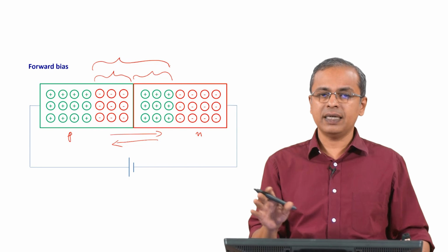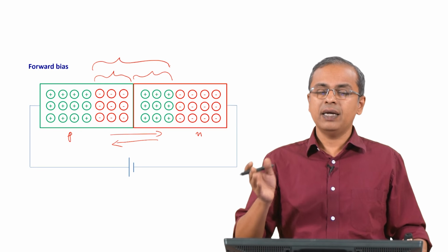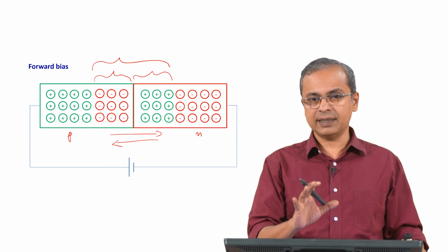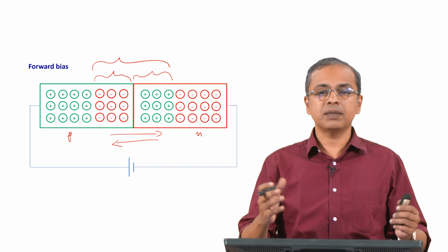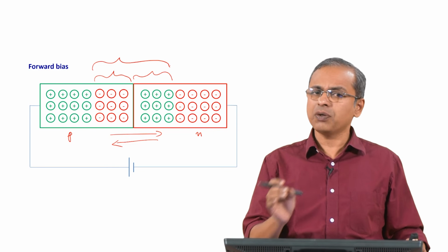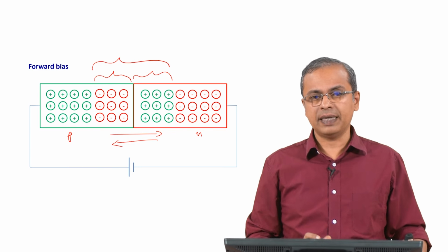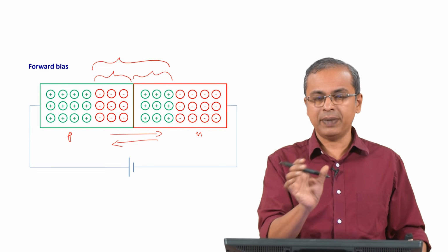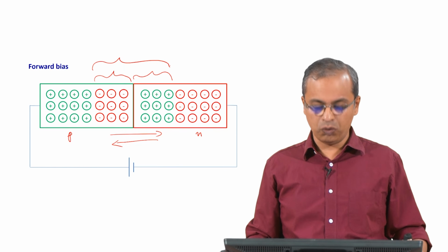and that is the reason why the holes do not diffuse all the way across into the n side, and the electrons do not diffuse all the way across to the p side, and that is how this differs from this being a metallic sample or even a junction between two metals. So, even there you will have some build up, but that is okay, that also has some aspects associated with it, but let us say two pieces of the same metal which are put together, then you can actually have essentially the electrons freely roaming around.